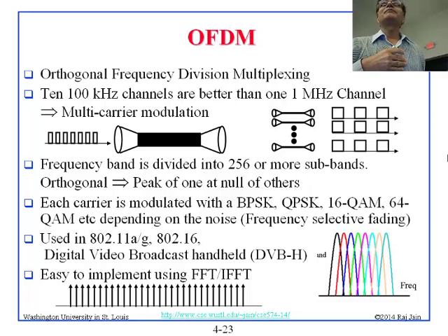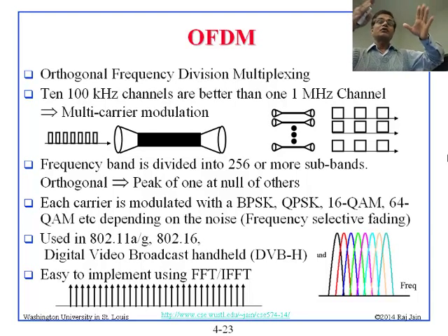1 megabit. I will get 1 megabit per second, right? So each bit will be how long? If there are 1 million bits in a second, how long is each bit? 1 microsecond, right? I mean, you can calculate, if I say how long, you could take the speed of light and figure out how long that is in meters, but let's not go into meters. Each bit is 1 microsecond.